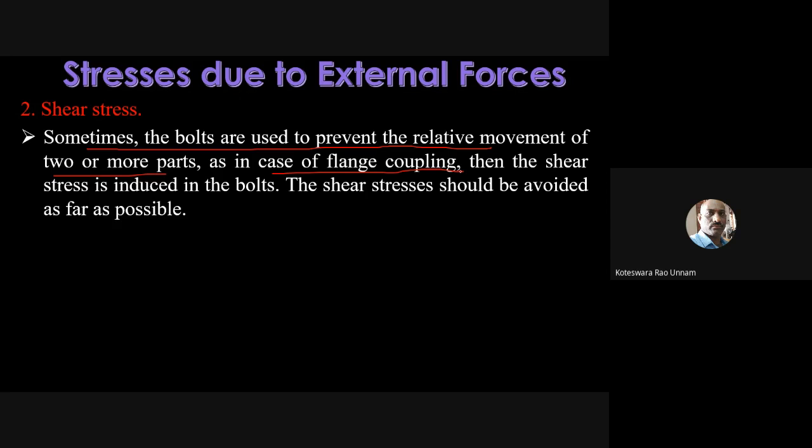The shear stress we can easily calculate. Shear stress is nothing but shear load divided by shear area. But generally, shear stresses should be avoided as far as possible. Because of this external load, we need to design a joint such that the shear stress on the bolt can be avoided.